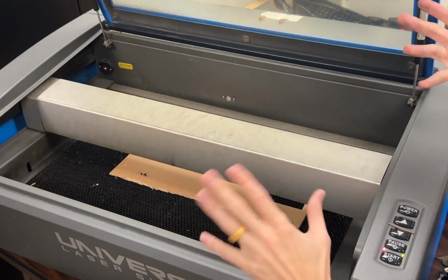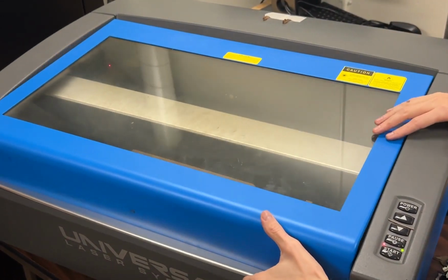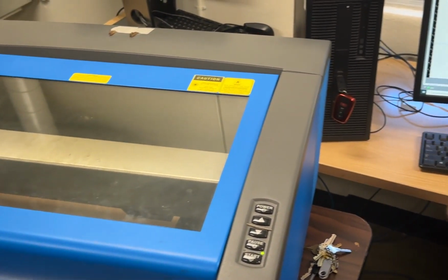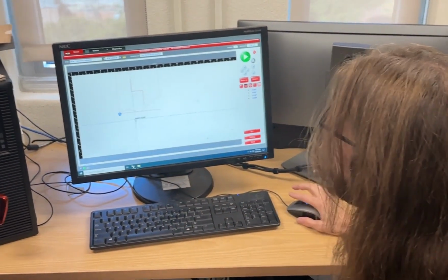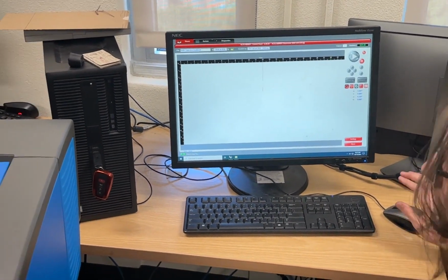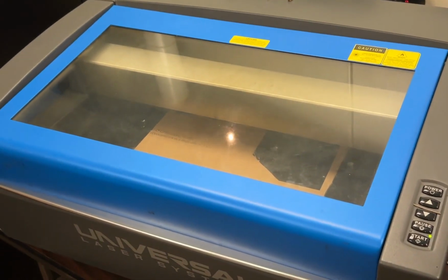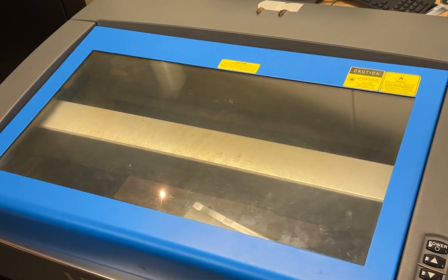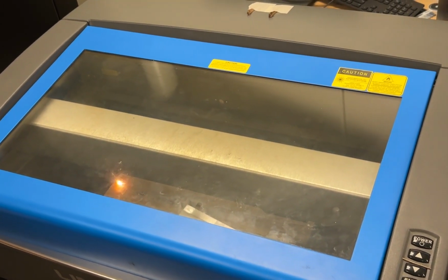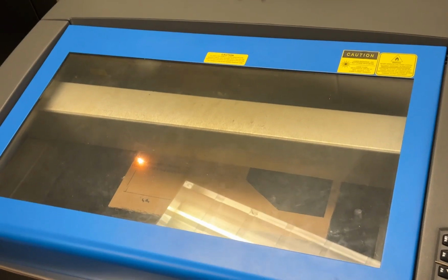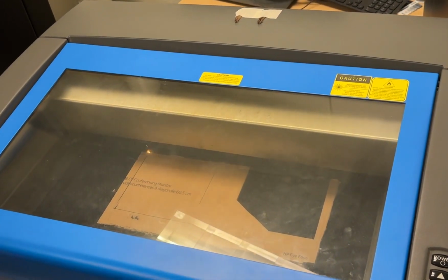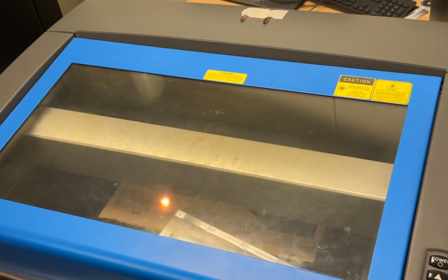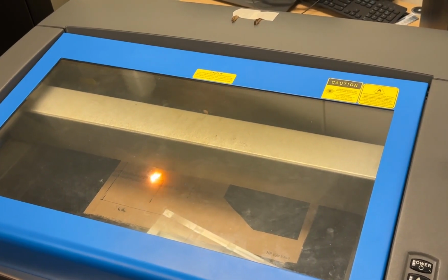And it looks like we're close enough to 2 inches that at least something's cutting. That actually worked out pretty well because, again, if that laser's off, it just won't cut. Or worse, it'll make a really big burn mark on the material. But that's looking pretty good. Let's press play. Let it do its thing. And a lot less fire, no? Still arguably there, but again, I don't feel like the material is going to get engulfed. And it lingers a little bit less. And as you can see, did you guys see the material move a little bit? That usually typically means that it cut. If you don't see the material move, I'm sorry.